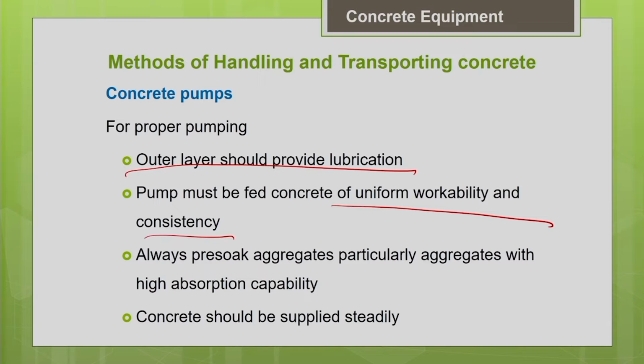Another important thing is if you are going to use lightweight aggregates for making concrete and if that is going to be pumped. You know that lightweight aggregates have higher water absorption capacity. So, when you use that kind of lightweight aggregate concrete for pumping, under pressure the aggregates will absorb more of the mixing water.